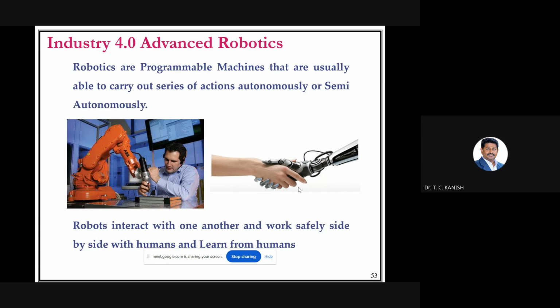Previously we saw the robotic system. Normally the Fanuc robot or ABB robot, or whatever the robots, they make a fencing. That means no one should enter the work volume while it is working. When people enter while it is moving, it will hit them and be harmful.